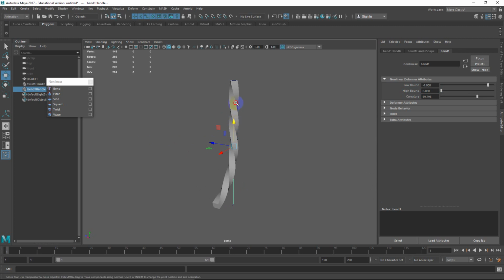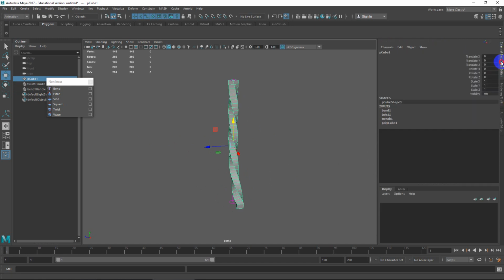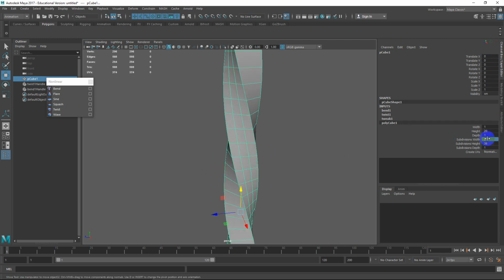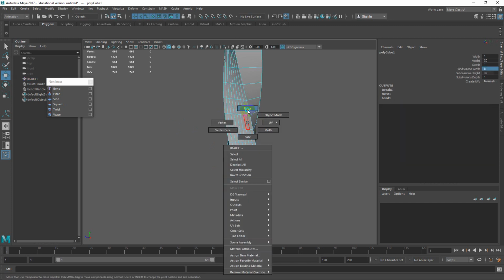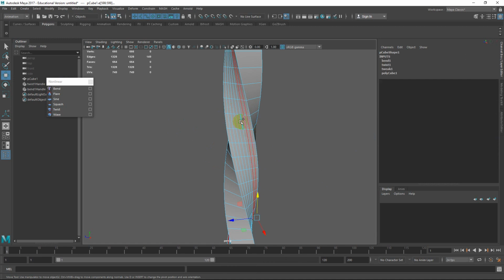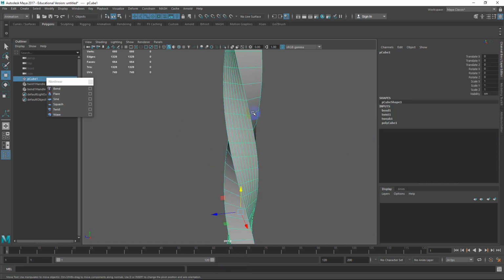So it's important to keep track of that, see where you need the mesh to go and what defines what. So I'll show you this. This is another idea of making sure. The reason I don't have any width or depth divisions is that if I add them, in this case, these extra edges, you see I just added, let's say, 8, they're going vertically, from left to right. So these loops don't really define anything in that surface. They're not adding any definition to the model. So these are cases where I would not add that to the mesh. I would keep this to its bare minimum.